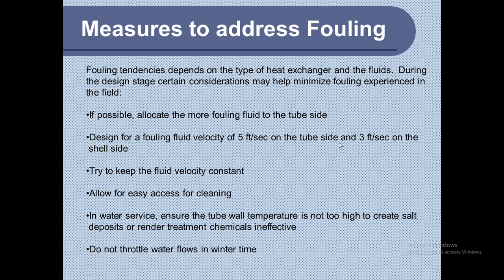In water service, ensure that tube wall temperature is not too high to create salt deposits or render treatment chemicals ineffective. So though we don't want salts to keep growing on the surface, we want our wall temperature to be not too high. And do not throttle water flows in winter time. So this is during winter.